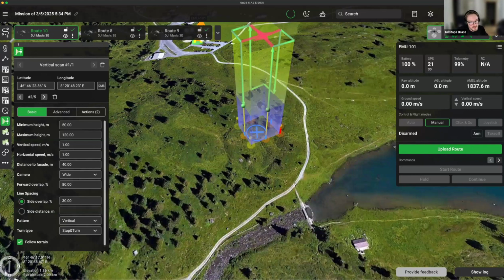So I of course know that, for different LiDAR sensors, different manufacturers recommend different calibration procedures. On one hand, there are custom calibrations you can do for each of them. On the other hand, I've spoken to some people who manufacture the IMUs used in LiDARs. Typically the LiDAR manufacturers don't make their own IMUs, so they buy the IMUs from somewhere. And the IMU is what needs to be calibrated.